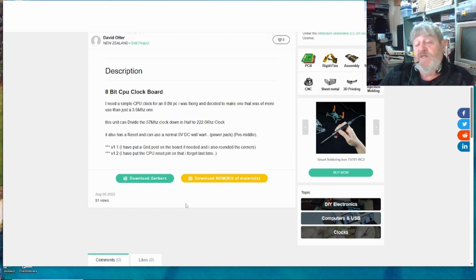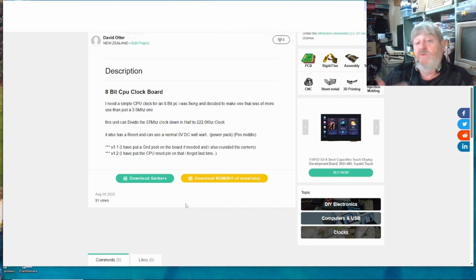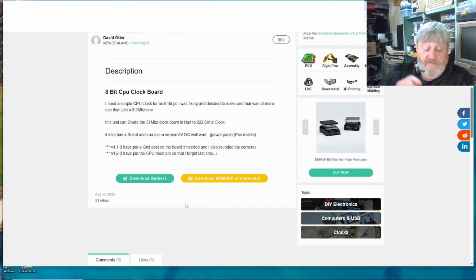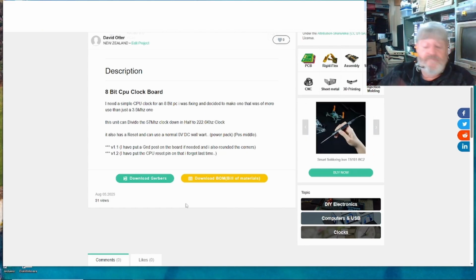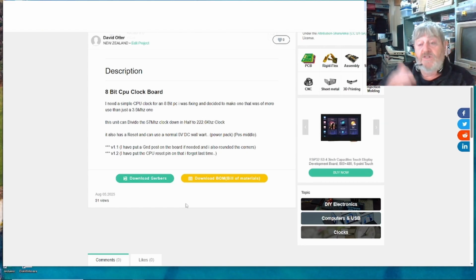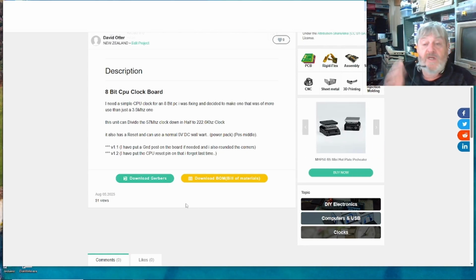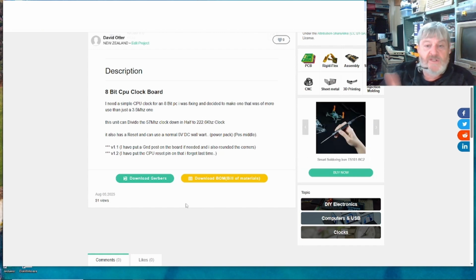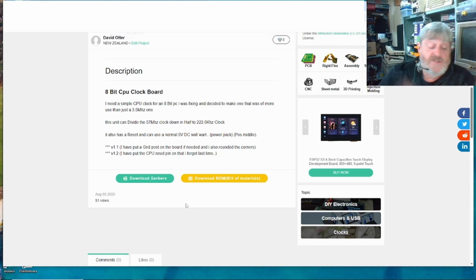The other thing is with this circuit you could get a higher speed 20 megahertz or 8 megahertz Z80, and with this board you could speed the chip up. So you could put a 20 megahertz Z80 in your board, and slowly increase it from normal speed up to see what happens to the system with the faster speeds, and find out where you can push the system to. If you like playing around with things, that's the way to do it.